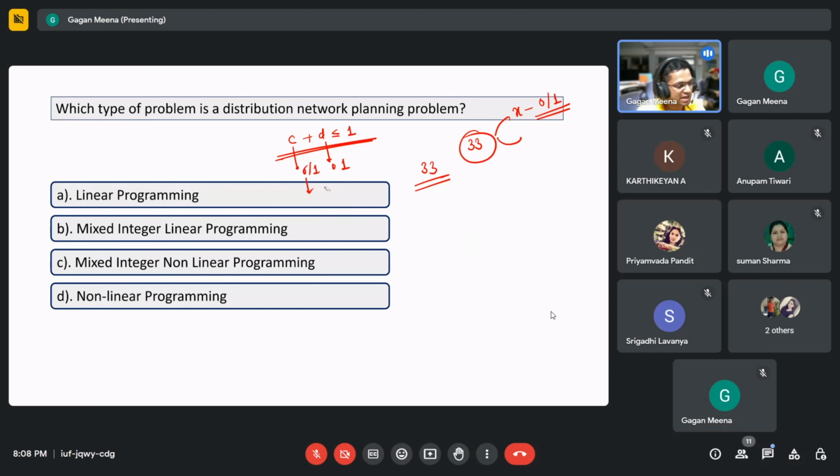Yes. So if we do network expansion planning also, we have an option whether we want to construct a line or not. With each line we have one variable eta, which can be 0 or 1. If it is required to construct that line, it will be 1, otherwise it will be 0. That will be decided by the optimization problem based upon the objective that we want to meet and the constraints that we have.